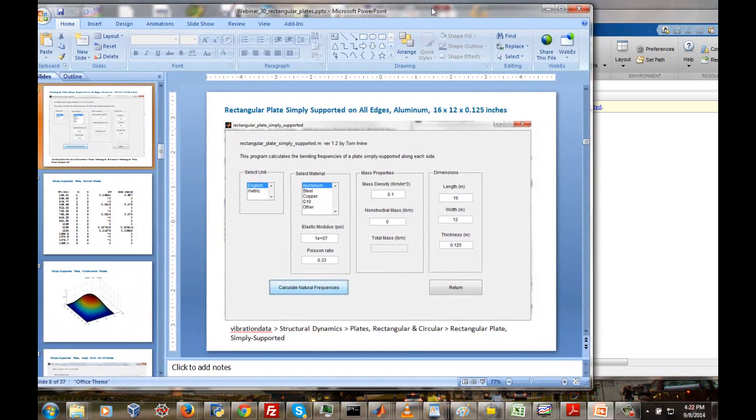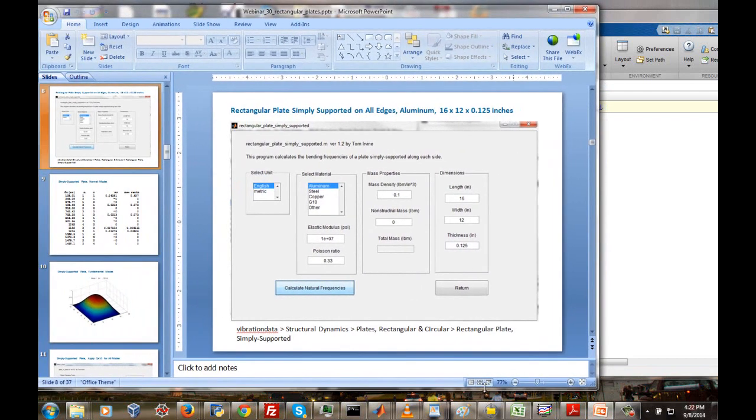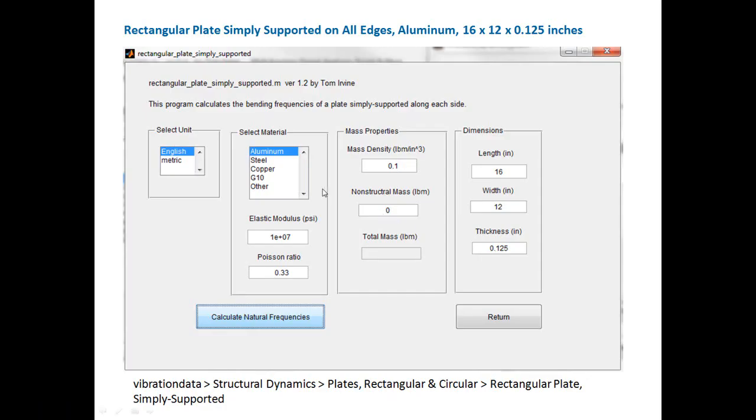If we were doing a circuit board analysis, I'd have said the circuit board material is G10, and selecting G10, the corresponding elastic modulus, Poisson's ratio, and mass density values would have come up. G10 is a fiberglass library material, and it's typically the material used for circuit boards.